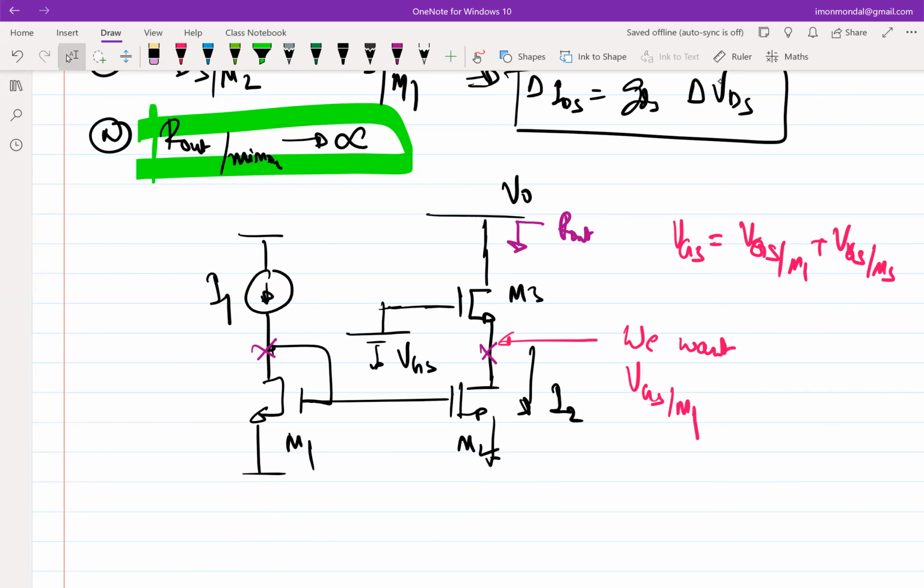It should be working at 0, it should be working at 70, it should be working at minus 40 degrees centigrade and all. So essentially, your design should be fail safe across change in wafer, on top of that change in temperature. So it might as well be that your threshold voltage is probably changing by plus minus 300 millivolt. That is also possible. Which means the current mirroring has to be accurate with respect to all these constraints that I am talking about. So putting a fixed VGS or putting a fixed voltage biasing is a particularly bad idea. Okay, so if that is the case, then the question is, what is the solution?